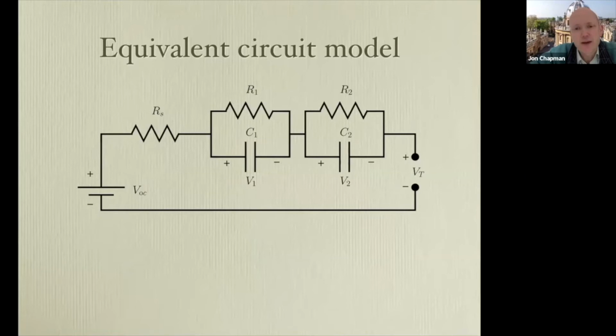For things like battery management systems, you might write down an equivalent circuit model, which is a set of resistors and capacitors typically. So you're now talking ordinary differential equations. On the one hand, I have a six-dimensional partial differential equation. And at the other end of the scale, I have a zero-dimensional equation. So zero-dimensional means the partial differential equation gives me an ordinary differential equation. And I want to try and use asymptotics to get from one to the other.